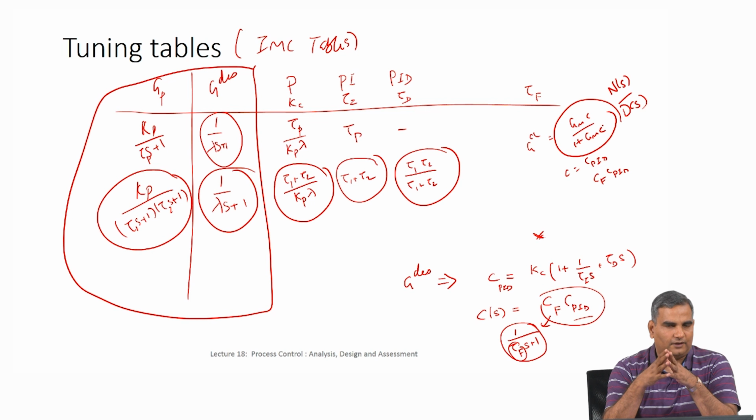So that is the first part of it, and then we saw how to analyze this, what are the advantages and disadvantages of these controllers through simple final value theorem. I showed that if you have a P controller, you will always have an offset. However, I also showed for some simple examples how the P controller is quite fast and reduces the closed loop time constant very efficiently when compared to the open loop time constant. So P controllers are quick acting, easy to implement, the disadvantage is offset.